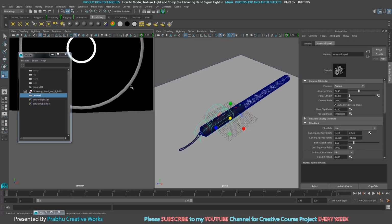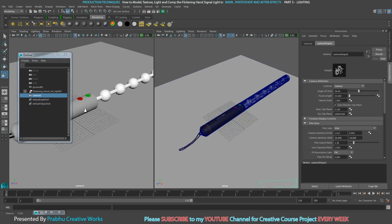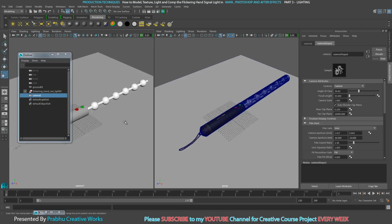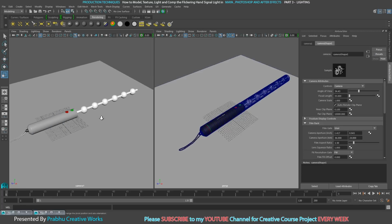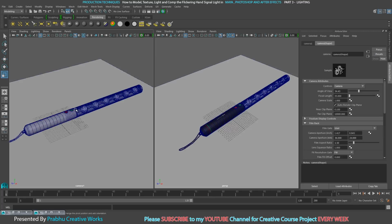perspective, and choose camera and click and drag your camera far away. See here, our camera will be moved when I navigate this one. So I will minimize my outliner. See here, I cannot see our wireframe. Go to shading and choose wireframe and shader and press 6 to see the texture over here.